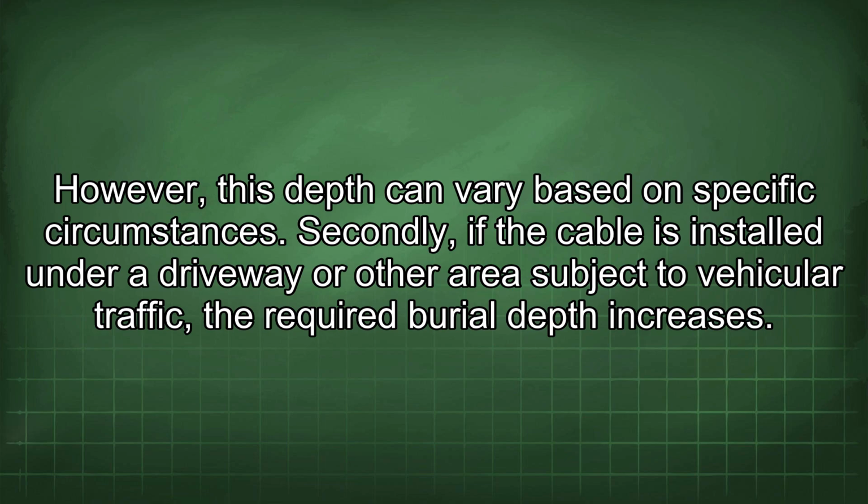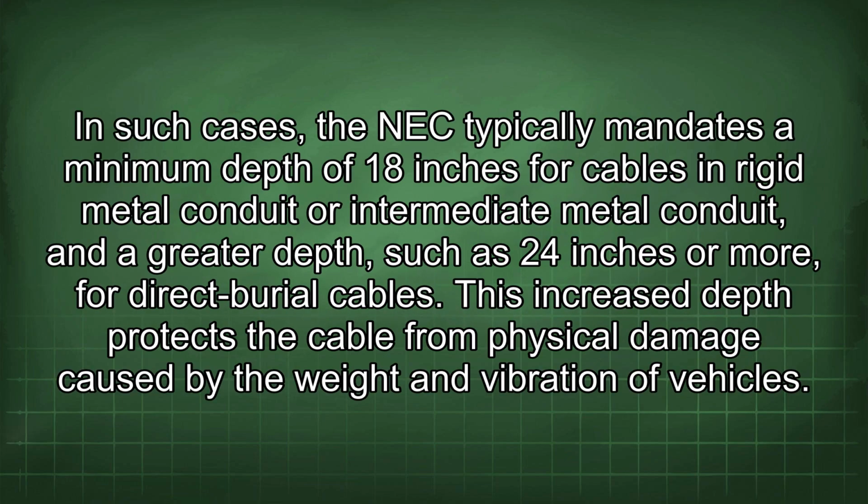Secondly, if the cable is installed under a driveway or other area subject to vehicular traffic, the required burial depth increases. In such cases, the NEC typically mandates a minimum depth of 18 inches for cables in rigid metal conduit or intermediate metal conduit, and a greater depth, such as 24 inches or more, for direct burial cables. This increased depth protects the cable from physical damage caused by the weight and vibration of vehicles.